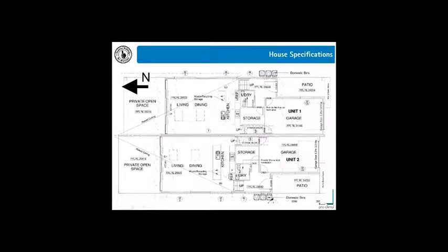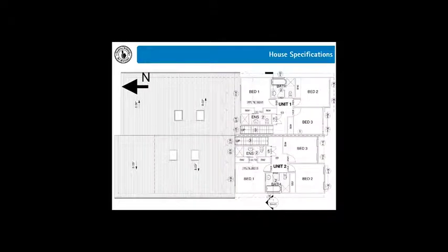We're going to look at the eastern duplex, the top one there, and we're going to look at the star ratings of that. So it's a 2-story duplex. The bedrooms are on the upper level at the front of the house. So when you look at the heating and cooling loads in that simulation of that duplex, you get around 2.5, 3 kilowatt hours per meter squared per year for heating and cooling. That's an 8.6 star rating.